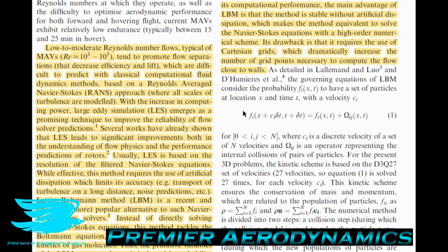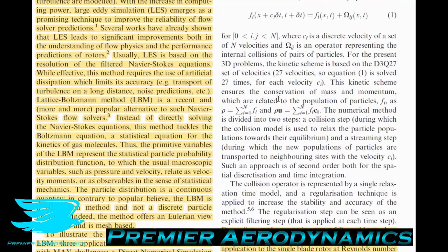So with the increase in computational power, large eddy simulation emerges as a promising technique to improve the reliability of flow solver predictions. Several works have already shown that the LES approach leads to significant improvements both in the understanding of flow physics and in the performance predictions of rotors. Usually, LES is based on the resolution of the filtered Navier-Stokes equations. What this means, if you're not familiar with LES, is that you're just looking at the large eddies and not the finer scale things. For the finer scale things, you just use modeling.